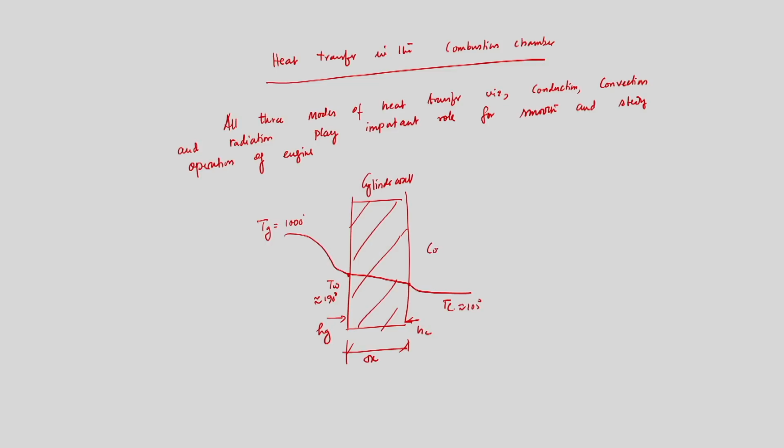So, this is the coolant. We need to supply coolant at the outer wall, and the coolant water will take away the heat from the wall and maintain the wall temperature within a specific limit. But the inner surface of the wall always needs to face the highest temperature of the combustion product, and that is why the material must be able to withstand it.